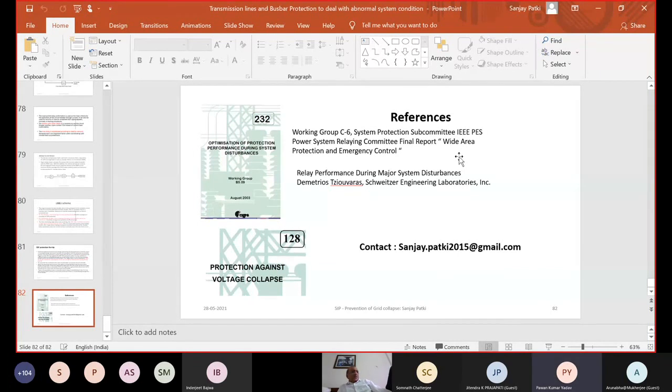No, I don't think so, because these inrush currents on the LT side, the 6.6 kV to 400 volt or other switching, will not be causing that much problem with your 11 kV to 33 kV main transformer protection. In any case, second harmonic will not result in any tripping on its own. It's only used in differential protection for restraining.